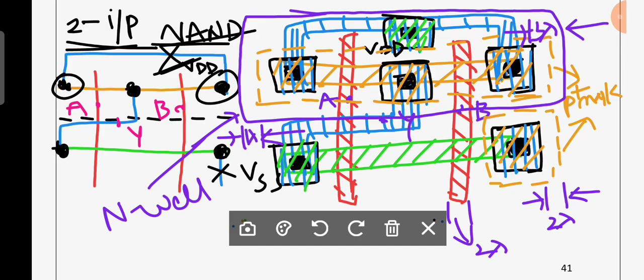And you have to represent what is the minimum size of contact area? That is 4 lambda by 4 lambda. You have to represent it very clearly. If it is not that clear here, then I will represent it at the bottom here, 4 lambda. And what is the minimum width of metal? Absolutely, that is 3 lambda. In this fashion, you have to give the rules.